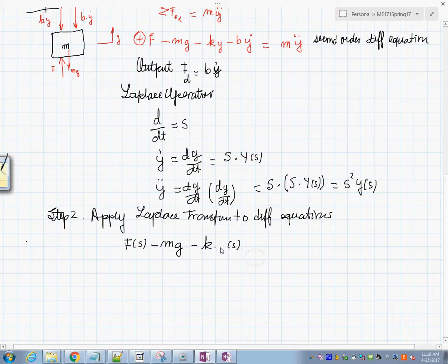Let's just be consistent about that so that we don't confuse them. And I am going to use it over here too, okay? And then minus b times s times Y of s. This is equal to m times s squared times Y of s, like that.